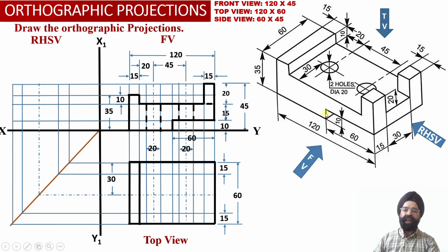Another thing we can observe, because of this rectangular slot which has been provided onto the base of the horizontal web on the right hand side, this rectangular face which is lying below this particular horizontal face will not be visible to the observer. So this will be obtained as a hidden line in the top view projections. Corresponding to this rectangular face, we are going to obtain a hidden line projection which will appear as an edge view projection corresponding to this vertical face of the rectangular slot which is available at the bottom of the horizontal web.